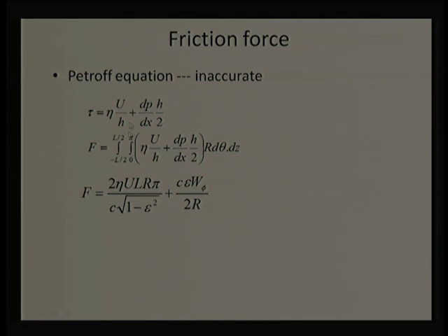We have discussed the Petrov equation, but for the bearing we are saying it is an inaccurate equation. I will demonstrate that after deriving this friction force formula. Friction force will depend on whether there is metal to metal contact, and we know for a hydrodynamic bearing there will not be any metal contact.